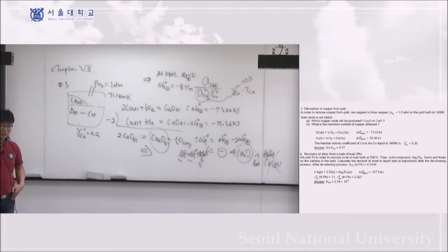Then you can add some element which makes a compound with the copper in the liquid state, so it makes a solid directly. Not pure solid, but Cu plus something else forming a compound solid phase. Then it just precipitates in the liquid, and you can remove all those solid particles.